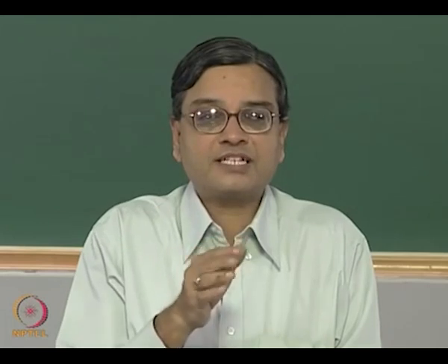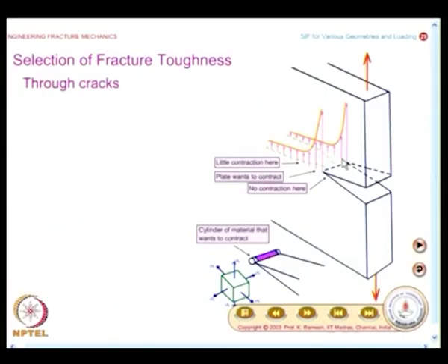For the purpose of discussion, let us consider the crack tip is sharp. So, you have sigma x equal to sigma y, and if the plate is sufficiently thick, you will also have stresses developed in the thickness direction of the plate, and that is given as nu times (sigma x plus sigma y). And if you look at the strain, strain will be 0. If you look at the stress, it will be nu times (sigma x plus sigma y).